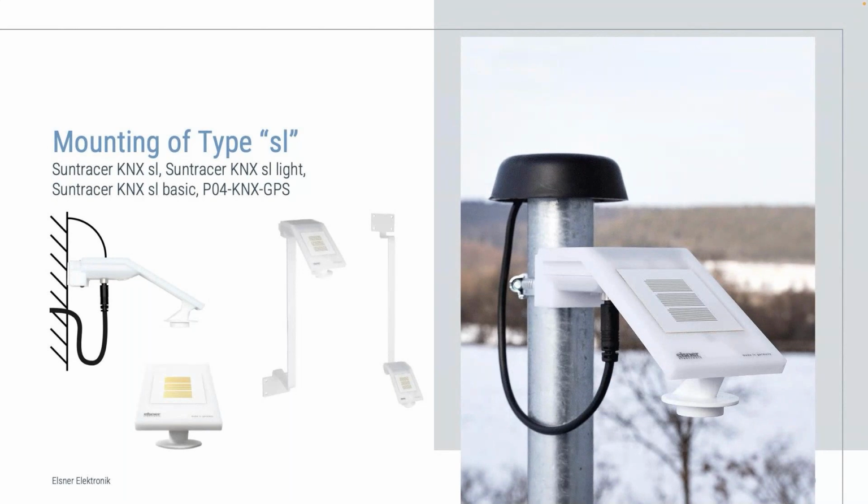The front of the weather station with the wind sensor must be oriented towards the south. In addition, a free space of at least 60 centimeters must be maintained below the weather station. The weather station cable should be routed in an arc to allow the water to drip off, as you can see on the picture.